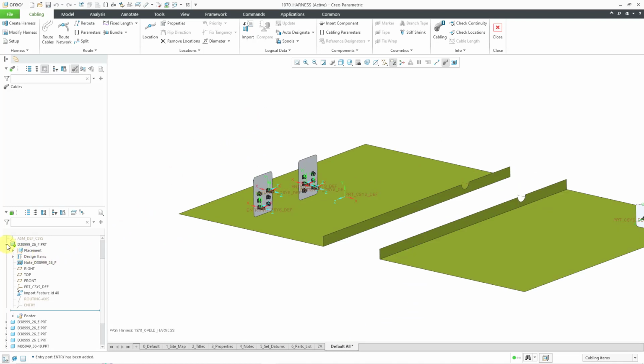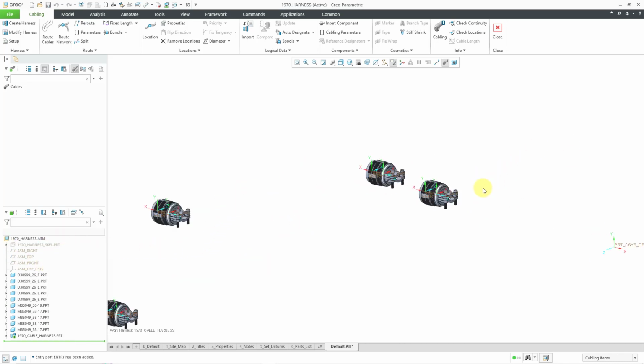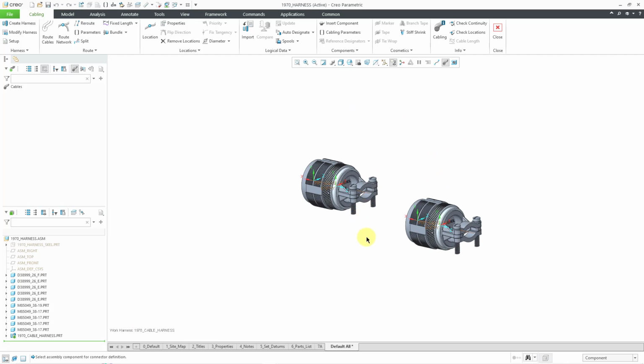And so for the next ones, I think it's going to be convenient if I hide my skeleton for a moment, just so that I don't get a whole lot of flashing when I am working in here. So now let's designate the other ones. I will go to the designate command, and then it asks me to select a component. So I will select my circular connector. Once again, I'll just hit the check mark and then entry ports, and let's select the one called entry and then click OK. I'll use 0 again for the internal length and a round grouping, and then done and done.